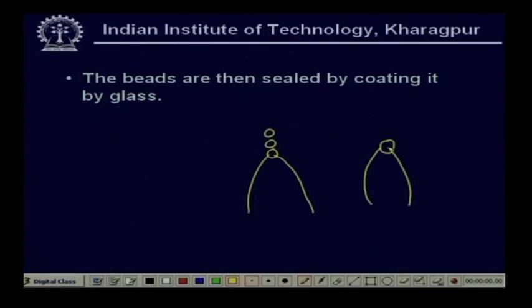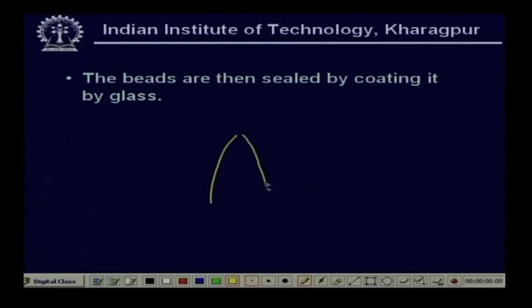So, what will happen? Let me erase first. The slurries are dropped on this one. So, it is put in a sintering furnace. Now, if you put it in a sintering furnace, what will happen? It will shrink, and this shrinking process will make very good electrical connections.